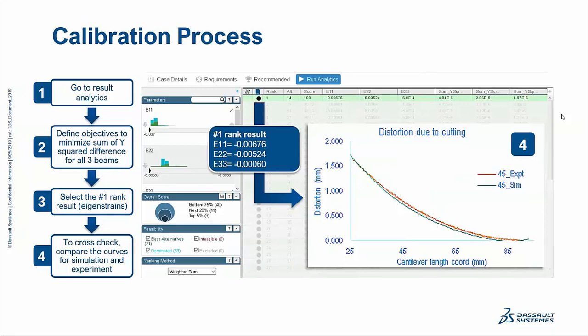and the resulting values are actually our eigenstrain tensor. Now, commonly, we only use the main components, the 1, 2, and 3 direction of the eigenstrain tensor. The cross terms are commonly discarded, although, as you can see, it's quite easy to obtain them and use them, but they're usually so small that they are simply discarded. It's an approximation anyways.